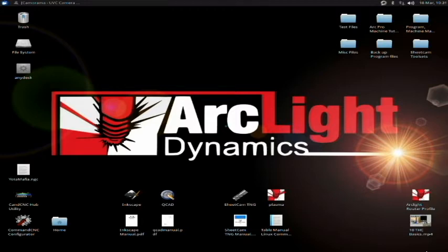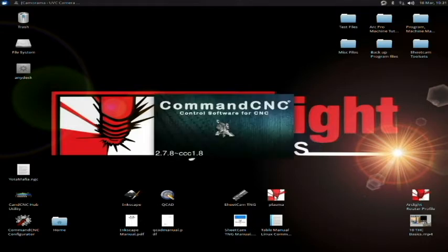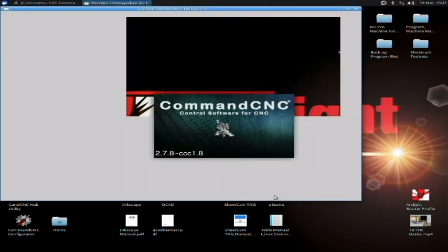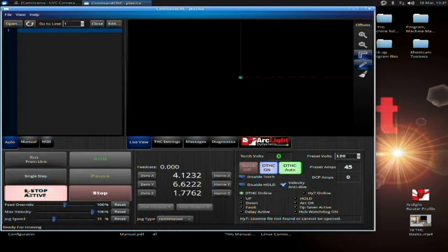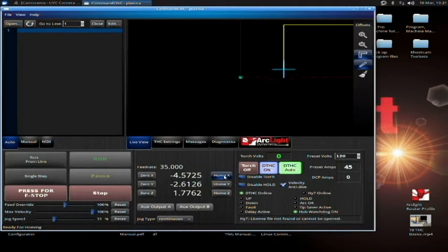In this series we're going to be loading up a code and talking about how to do what's called a dry run. So first thing I'm going to do is power up my system here. If you already have your system powered up, you don't have to worry about it. Pull it out of e-stop. I already have my motor power on. And I'm going to set my machine home. Now, if you've already set your machine home, your machine's been powered up, you don't need to do this. But this is just replication to ensure that, yes, in fact, we have set our machine 0.